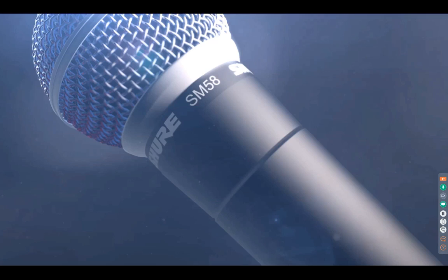That pocket of air gets smaller and forces more air up into the cartridge. And it stiffens that diaphragm and coil assembly as you're inducing handling noise upon the mic. As you stiffen that diaphragm and coil, it prevents it from moving while you're exerting your handling noise upon the handle of the mic. And it requires about 300 pages of math to figure that out. And then it requires a whole bunch of time and effort to execute that math within actual parts.